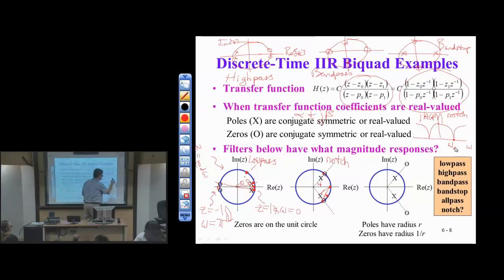And so I'm not drawing this very well to scale because this goes all the way out to pi. Right? We plot the frequency response from minus pi to pi, or we can go 0 to pi. Here I want to go minus pi to pi just because it's a little more visible to see the notch in action. What's this left frequency that's being notched out? Negative omega naught. Right, so this is a way to remove a certain frequency. We do this with power line frequencies, 50 hertz, 60 hertz, depends on the country, or any other interference that's sinusoidal or periodic that's at a certain frequency. We can notch it out this way.